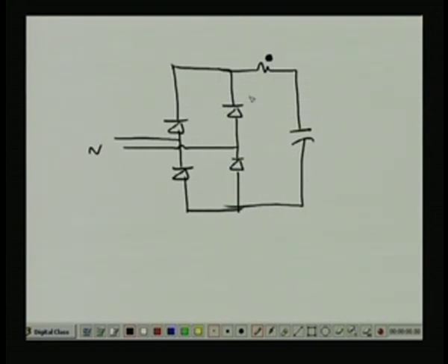The value decreases, which is what I want, because otherwise it is a wastage, a loss of power that will never be utilized. The efficiency of your power supply will deteriorate just to protect the 4 diodes. You may say, sir, I will use some fuse here, but a semiconductor device is to be protected by another semiconductor device, please note that. You cannot do that.